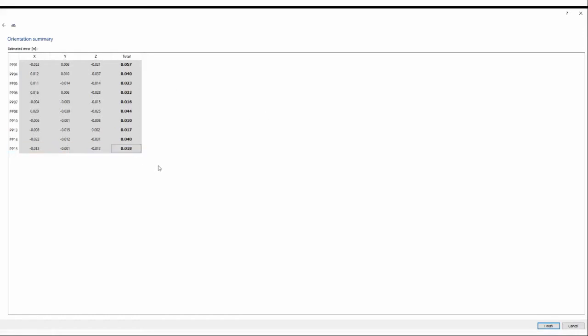So, of course, if we also used ground control points to georeference this data, then the end result would be even more accurate. So we have a sort of catch-22 situation. If we want to know what kind of accuracy we will get from the RTK drone, then we need to measure some points on the ground. If we don't, we may not know the accuracy of the 3D data.